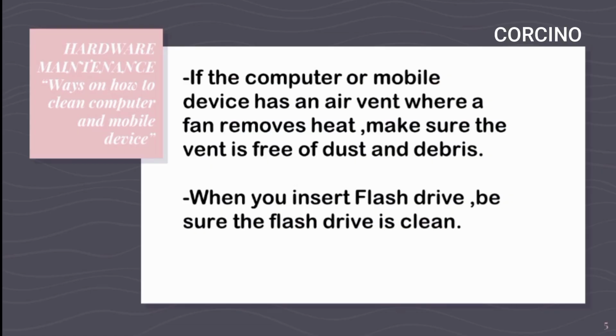Fifth is, if the computer or mobile device has an air vent where a fan removes heat, make sure the vent is free of dust and debris. A blocked vent can prohibit heat from escaping, which ultimately can cause the computer or mobile device to overheat. If the air vent is dirty, contact a trained professional to have it cleaned properly. Improper cleaning of an air vent can result in more debris entering the computer or mobile device.